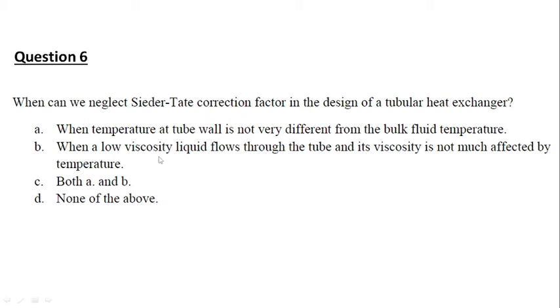But here the statement is that a low viscosity liquid flows through the tube and viscosity is not much affected by temperature. So in both these cases we can neglect the correction factor in a tubular heat exchanger. So the answer will be option C.